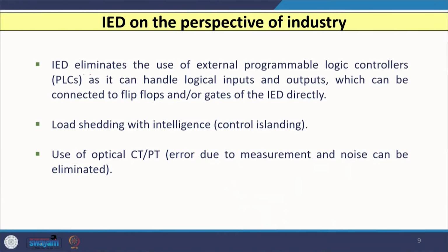Now, let us consider how we can use IED as far as the industry perspective is concerned. So, IED eliminates the external utilization of programmable logic controllers, as it can handle the logical inputs and outputs. So, this type of feature is not available in the previous generation of relays. So, industry people can use IED without utilizing external programmable logic controllers.